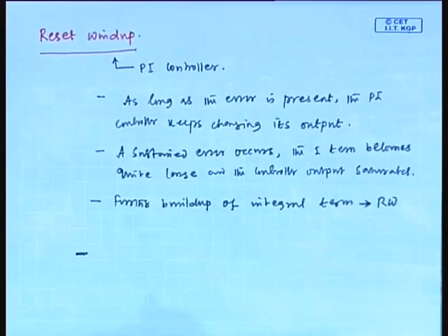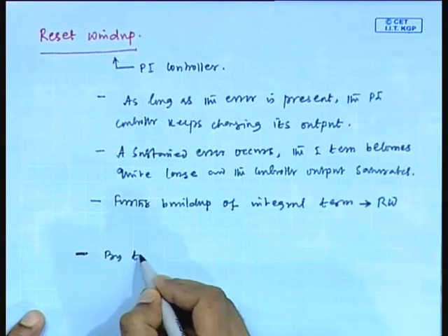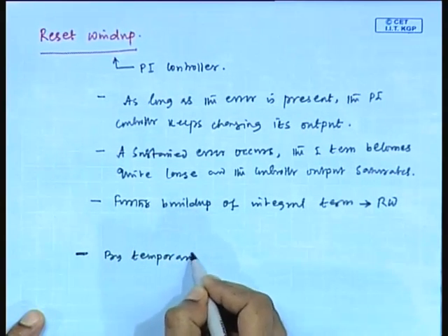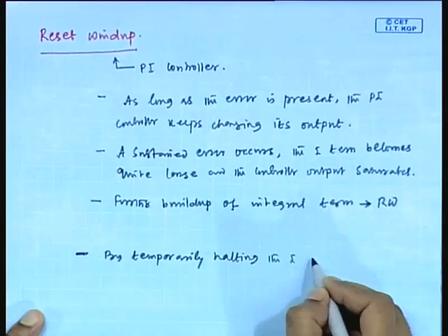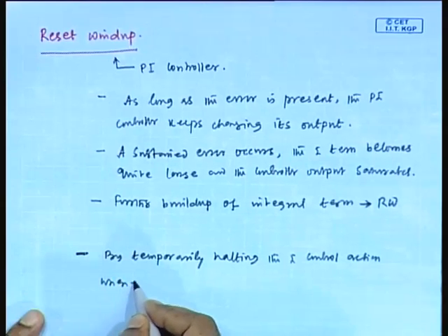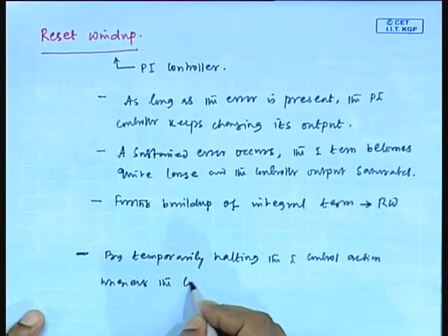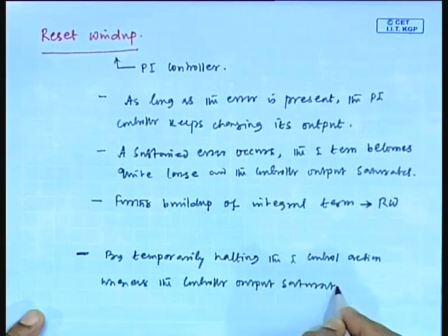Reset wind-up is reduced by temporarily halting the integral control action whenever the controller output saturates.